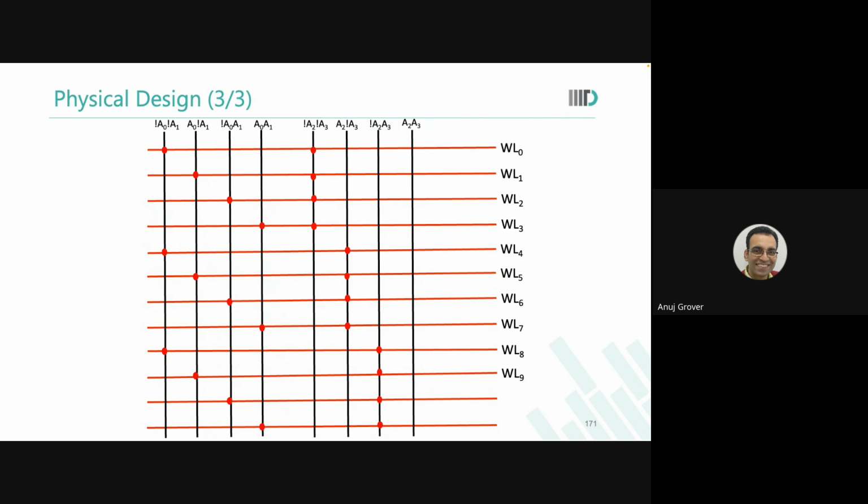So, suppose over here I have to make a P well or an N well. Let us say whatever we have to make. Okay. What do I need to do? I need to do some doping in that region. So I will need to create a mask where when the ions are projected from the top, they don't touch the silicon over here.